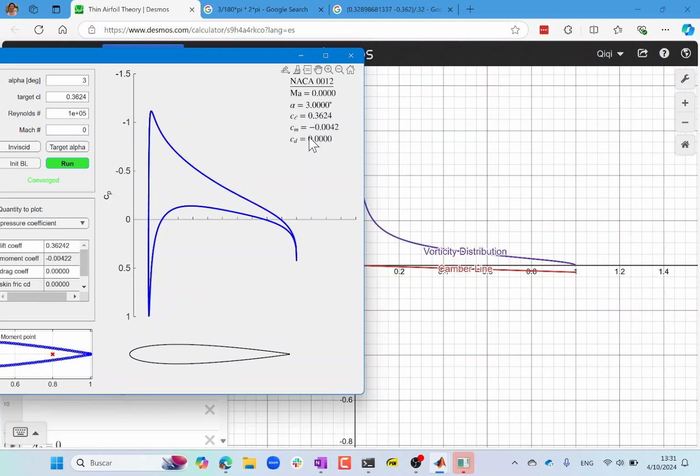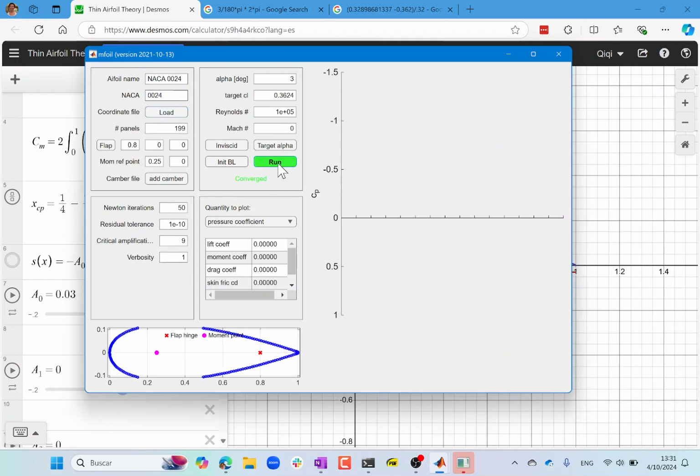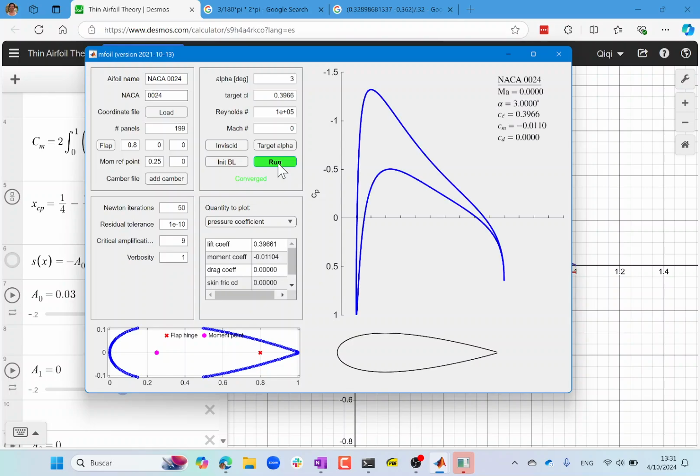Okay, so let's actually look at two different things. One is an airfoil that's even thicker, to get a sense of how much more error we can get. So instead of a NACA double 12, we enter NACA double 24. It's going to be a pretty fat airfoil, something you would expect not from an airfoil used as a wing, but something used as a fairing to make something more aerodynamic.